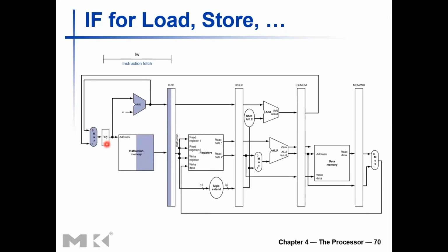So any updated value to be written to the program counter must have been ready by the previous rising edge, right? So by the rising edge at the start of this clock cycle, a new value to be written into the program counter is ready. Then, as soon as the rising edge hits, your program counter gets updated.